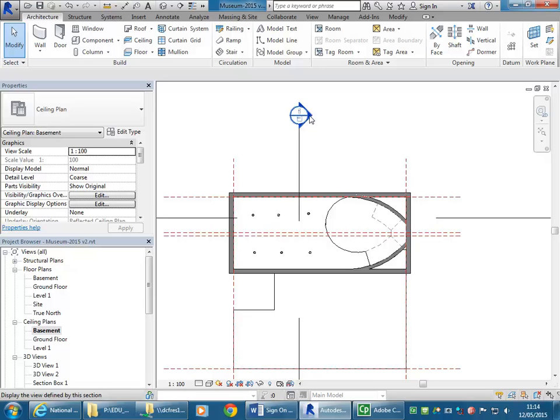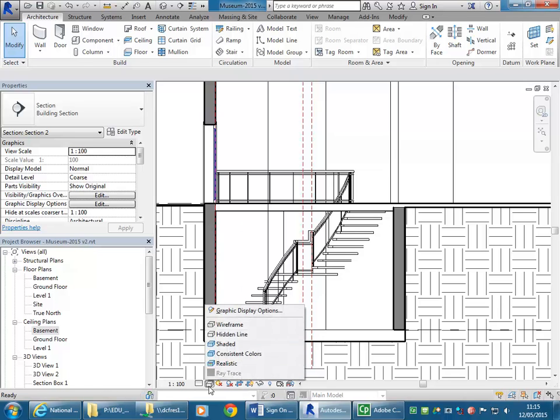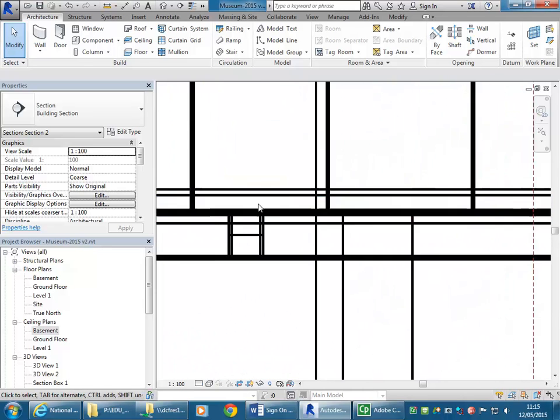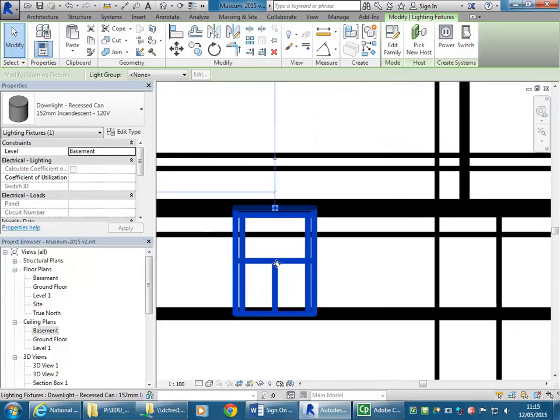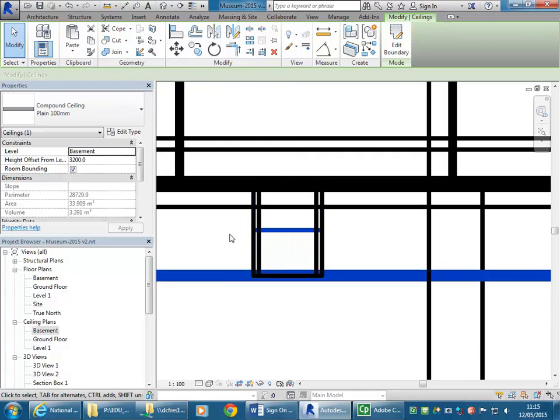Okay, so I'm going to go back into the section view, and there I can't see the light because it's behind my section line. But if I go to wireframe, then I can show you the light, and you can see it's just got enough room to go, just because I know how this light works, it goes into the floor, which isn't a problem, but the light source I know from experience is just there, and it can't go into the floor if you want the light to illuminate your scene. So you need to have the light source only within the ceiling, and that's why I made the ceiling in that way. Okay, so you can see there the ceiling thickness is to there, and the light source is just below it.